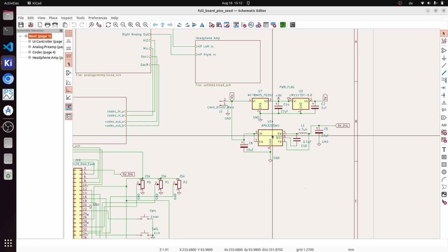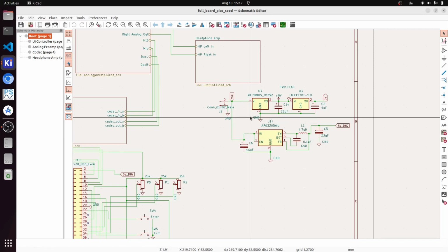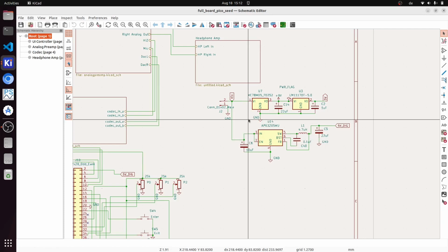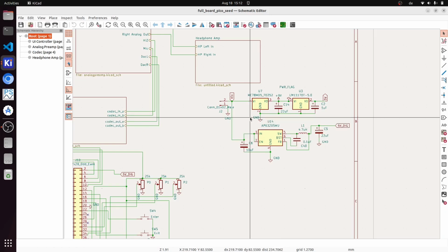This is then converted through a half-wave rectifier into plus and minus 12 volt, which I thought was a good idea, since I was used to working with plus minus 12 volt when building this analog modular synthesizer, but it has proven that this wasn't really a good idea for this device, because there was still hum inside, and I needed to add really big capacitors to get rid of the noise somehow, but it still remains in some settings.